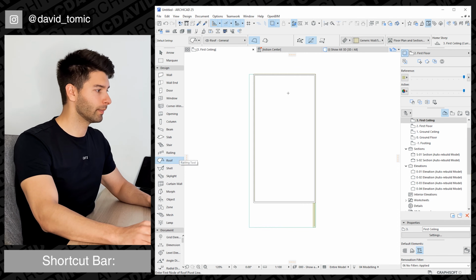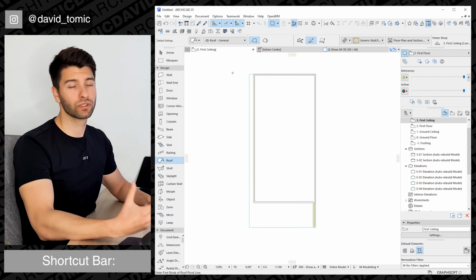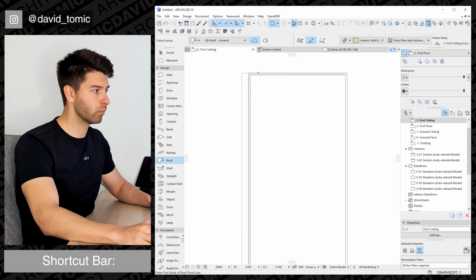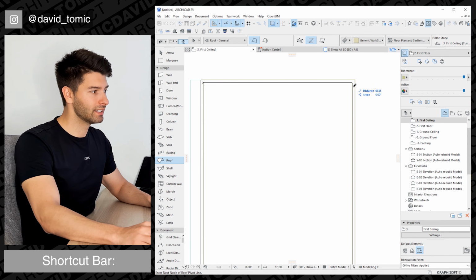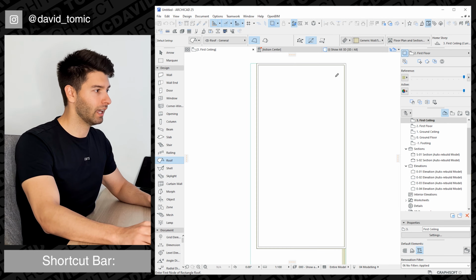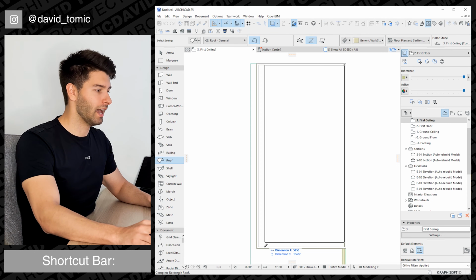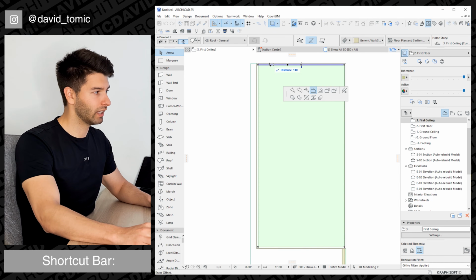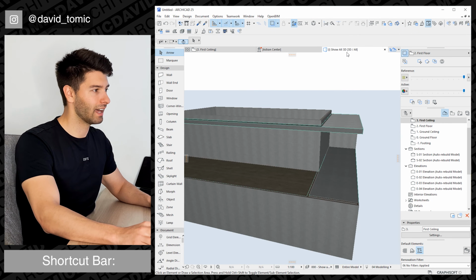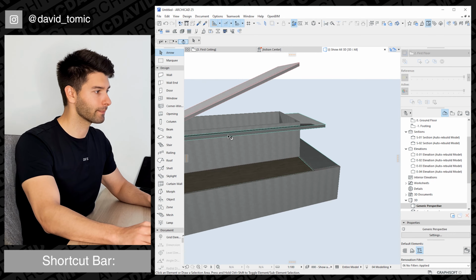Now to create our roof, I'm going to go to our roof tool, and you always want to start with your pitching point at the lowest point, which means coming over to this side of the wall, starting on the inside of this leaf and clicking on the actual inside, coming all the way across, drawing our roof, and then most likely extending that another 110 mil back.